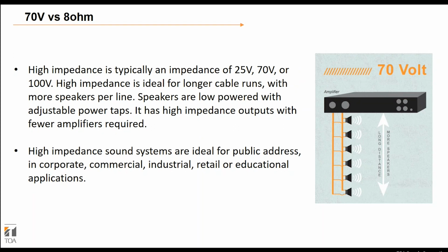There's also usually fewer amplifier outputs required because you're not having to run an individual cable run for each speaker or pair of speakers as you would on a low impedance system. These types of systems are ideal for public address and background music and things like that in corporate, commercial, industrial, retail, or educational applications. Basically anywhere where you need to have a lot of speakers, but you don't need a lot of amplifiers. You don't have a lot of processing necessarily in most cases in front of them.